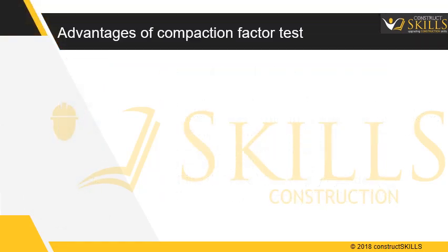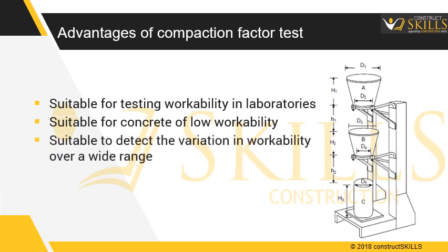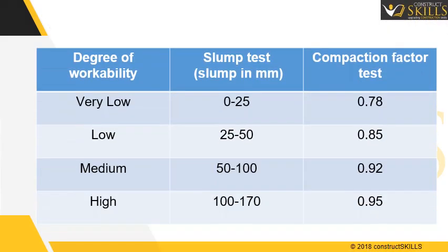Advantages of compaction factor test. Suitable for testing workability in laboratories. Suitable for concrete of low workability. Suitable to detect the variation in workability over a wide range. The results are more precise and sensitive. The table explains the degree of workability according to test results.